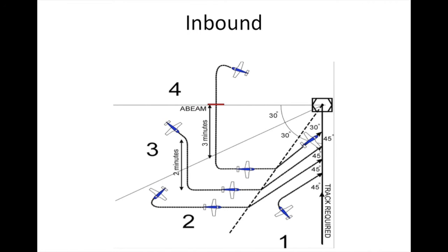Inbound, all I care about here is if I'm within 30 degrees or 60 degrees or higher. Anything higher than 60 degrees, I'm going to fly in the opposite direction of that inbound radial. And then once I'm 60 degrees from that radial, I'm going to turn 90 degrees towards it. Once I'm 30 degrees from it, I'm going to turn another 45 degrees and intercept it. And that's how you properly intercept or track an inbound radial if you're instructed by ATC. And all it depends on is where you are when you're instructed to do that.